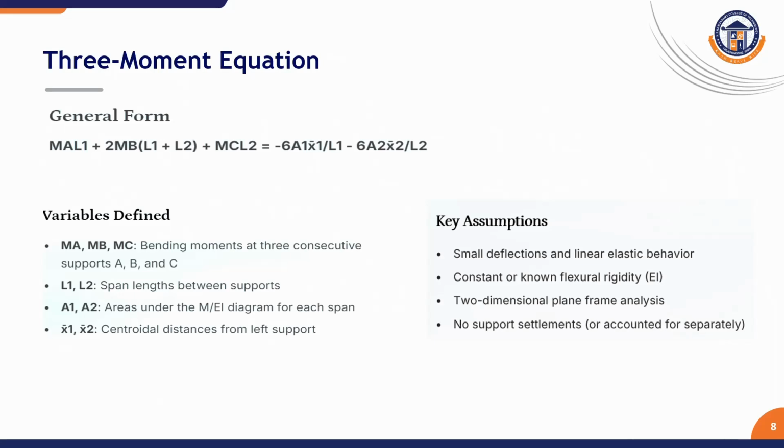By writing one equation for each set of three consecutive supports, we can form the system of equations and solve for the unknown support moments. Once the support moments are known, the entire beam can be analyzed using the basic equilibrium equations.